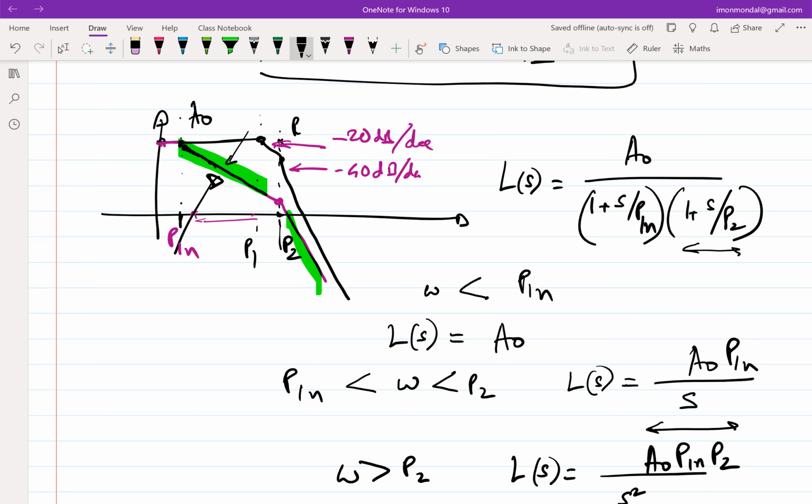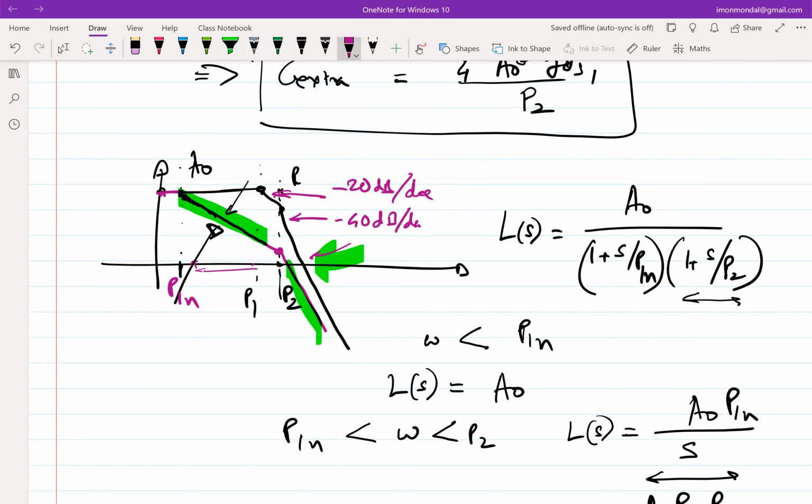That is happening because the closed loop poles are very close by under the condition of the gain also being very high. This essentially means you will have a minus 40 dB per decade roll off around omega u loop. This was the original omega u loop. So this is not an integrator-like response around omega u loop.